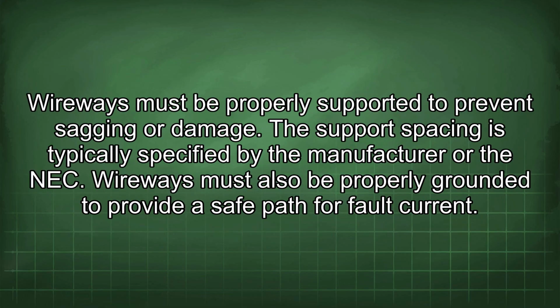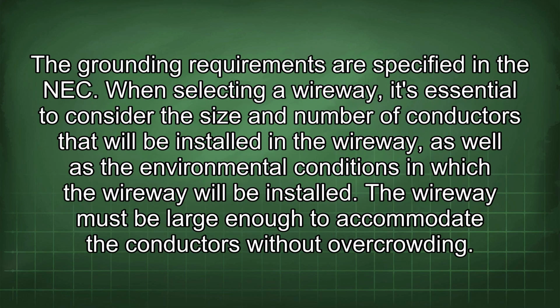Wireways must be properly supported to prevent sagging or damage. The support spacing is typically specified by the manufacturer or the NEC. Wireways must also be properly grounded to provide a safe path for fault current. The grounding requirements are specified in the NEC.